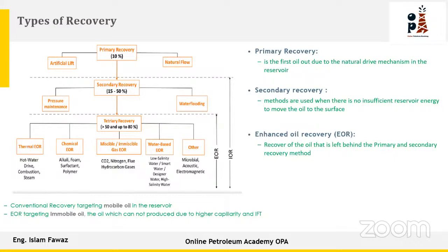So we are looking after the primary recovery and secondary recovery. We're looking for the oil left behind, and we need to maximize the recovery from 50 up to 80% recovery factor due to the sum of the enhanced oil recovery that you make in your reservoir. Improved oil recovery is a combination of secondary recovery and tertiary recovery, but EOR is a tertiary recovery only targeting the immobile oil in the reservoir. So conventional recovery targets the mobile oil from secondary recovery up to tertiary recovery, but EOR is targeting the immobile oil from the reservoir.